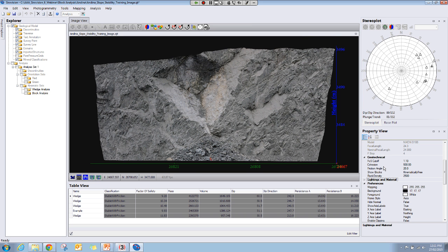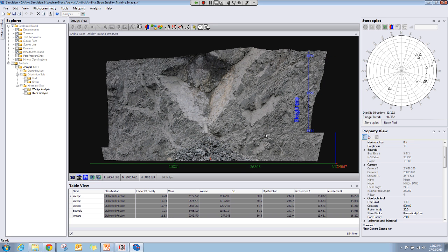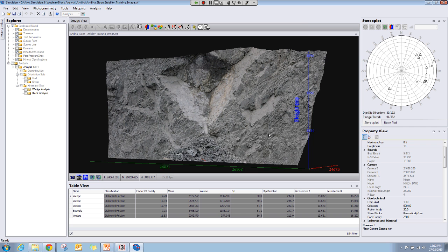You'll probably find it quite difficult to read that, but we would input cohesion, rock density and a friction angle into that 3D image or 3D model, and it would apply those values to all the joint surfaces in the model. So it was really a single domain analysis. So when we would then map structure on that surface, like this,